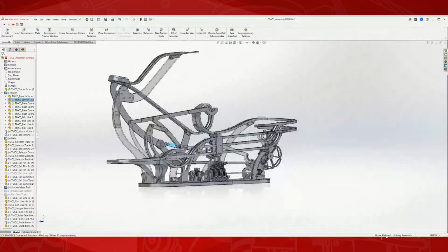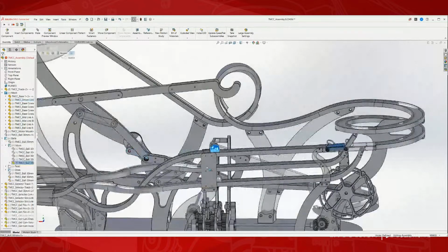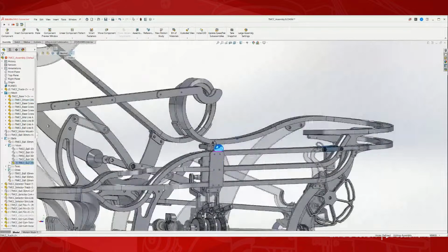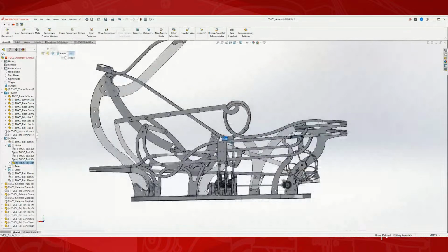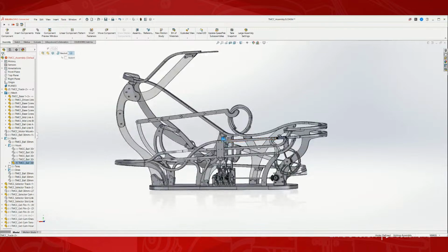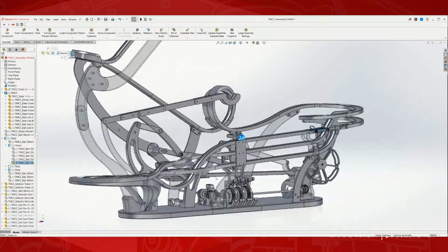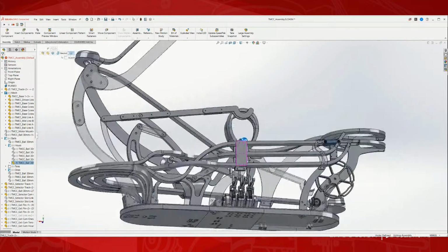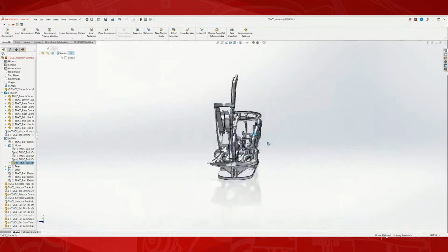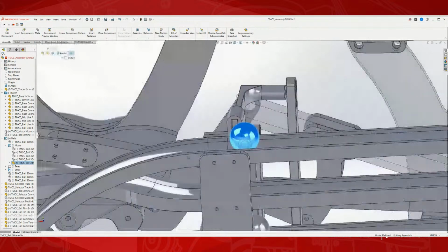And often there's some sort of fixed dimension. In this case, it was the balls that I was using, which were 30 millimeter balls. I chose these because I wanted the thing to be big, but I was originally thinking 2-inch diameter balls, or 50 millimeter. And that meant that this thing would have been absolutely massive in total. So I decided to scale it down to these 30 millimeter balls, but this is what allowed me to start designing everything around that. So the overall height, the spacing that I needed these tracks to be, the width of the tracks, and the profile and how they roll. And so after selecting the ball, I was basically able to start designing off of that.